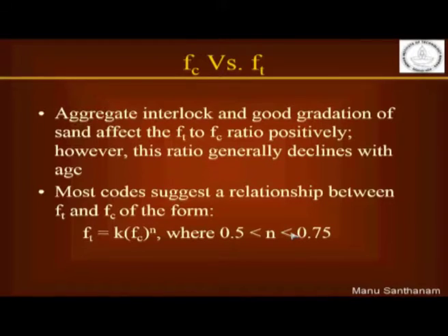So, the data that you have for your set of concretes may or may not follow the same relationship. So, do not believe these relationships blindly, they are just a means for suggesting some equations to use when you do not have the necessary capability to conduct a test. Okay. As far as possible, the test should be conducted to determine the actual properties rather than to use these kinds of relationships.